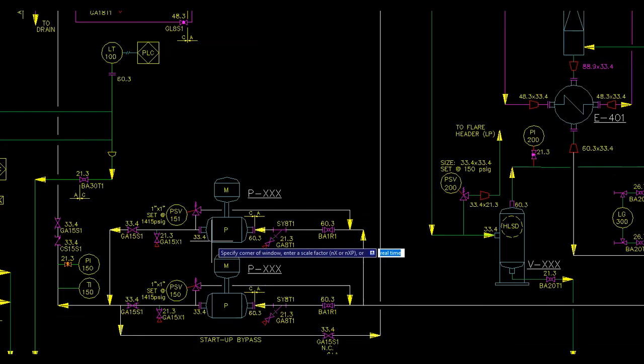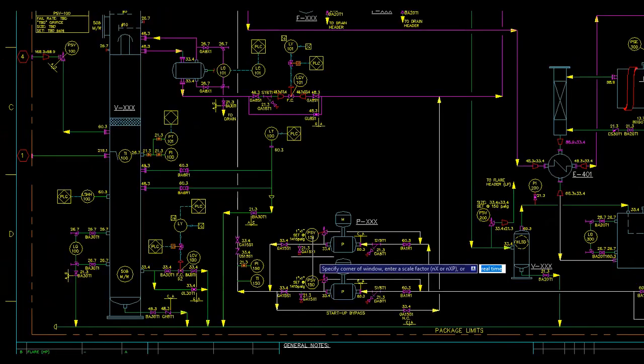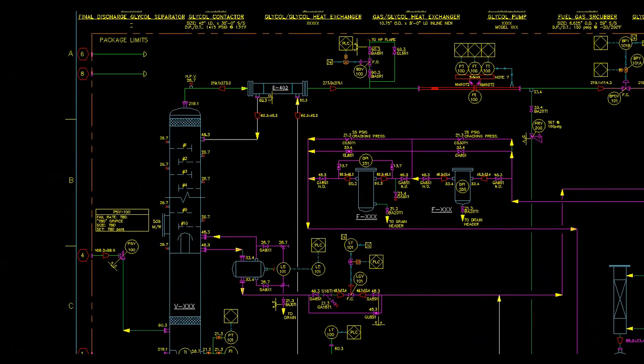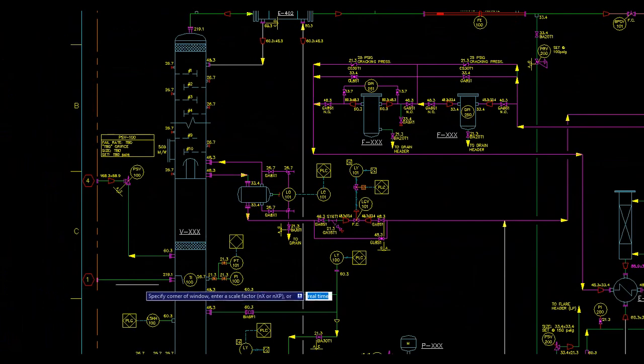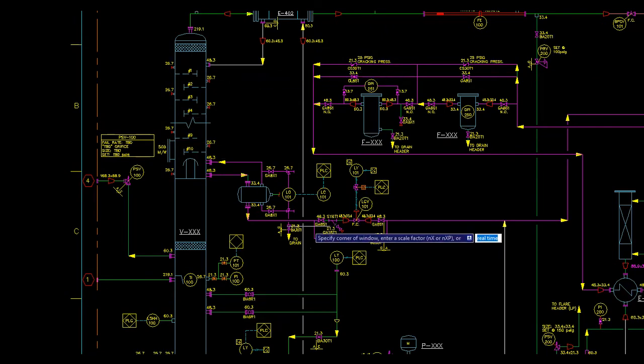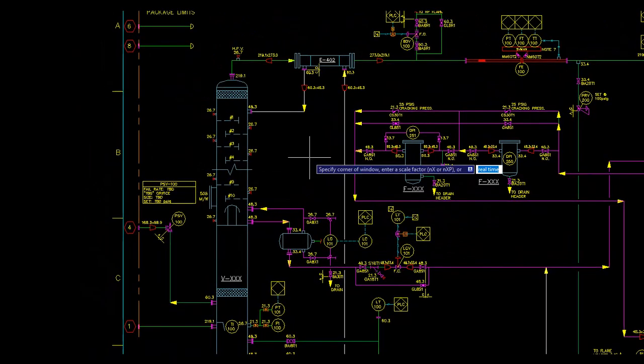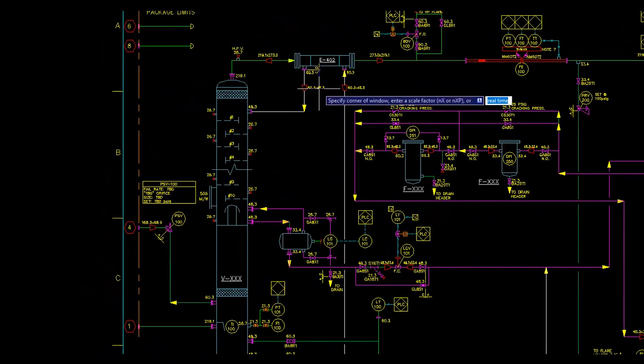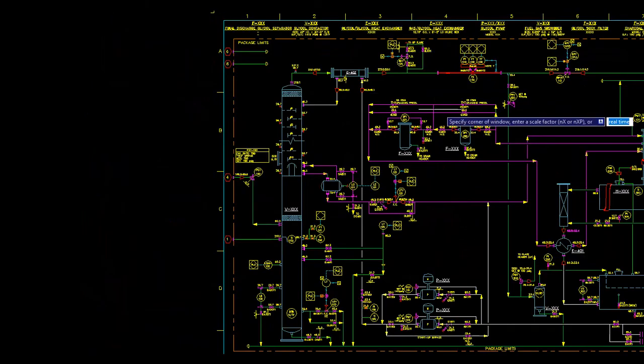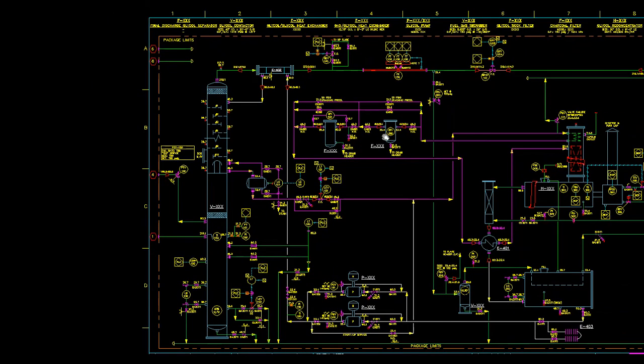The temperature of lean glycol is further dropped in the gas glycol exchanger such that the temperature difference between the inlet gas and the lean glycol is a maximum of 10 degrees Celsius. If you can't meet this kind of endpoint temperatures in the lean glycol, then the dew point will be in question. The cooler the lean glycol gets, the better is the dew point of the sales gas.